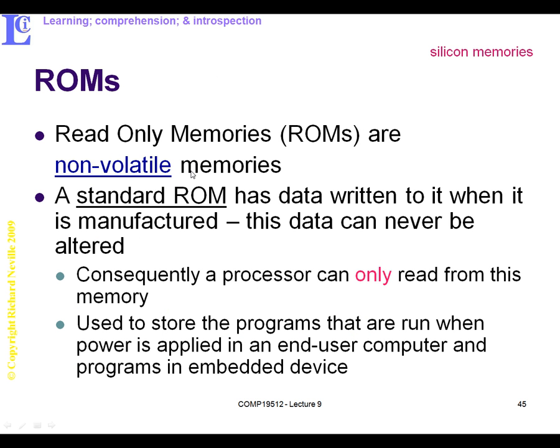So non-volatile memories are read-only memories. So a ROM is a non-volatile memory. And there's a standard ROM, which is made by manufacturers, and the important thing to realize is you can't change it, you can only read from this memory. And these are devices which, even though it's beyond the scope of the course, you program into them the BIOS, the basic input-output system for a PC, which will then load the operating system. You can only read from them. The manufacturer will program them, and they will be in the end-user computer embedded in it.